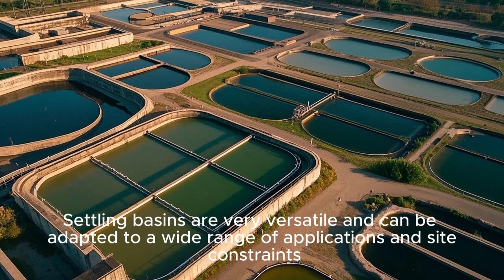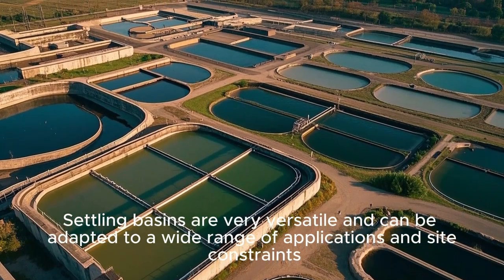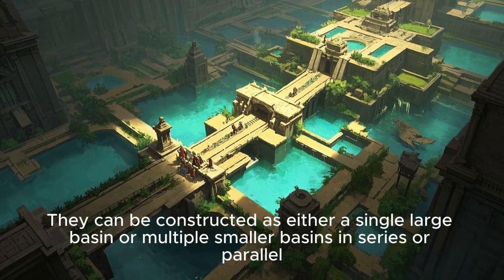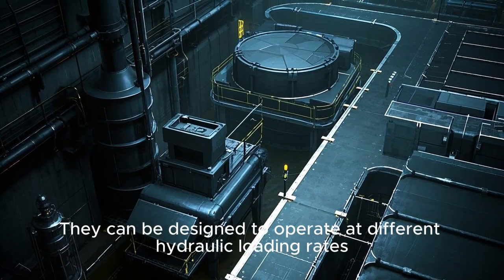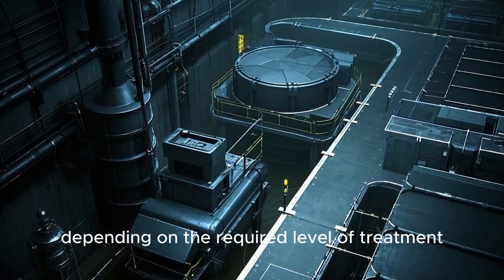Settling basins are very versatile and can be adapted to a wide range of applications and site constraints. They can be constructed as either a single large basin or multiple smaller basins in series or parallel. They can be designed to operate at different hydraulic loading rates depending on the required level of treatment.